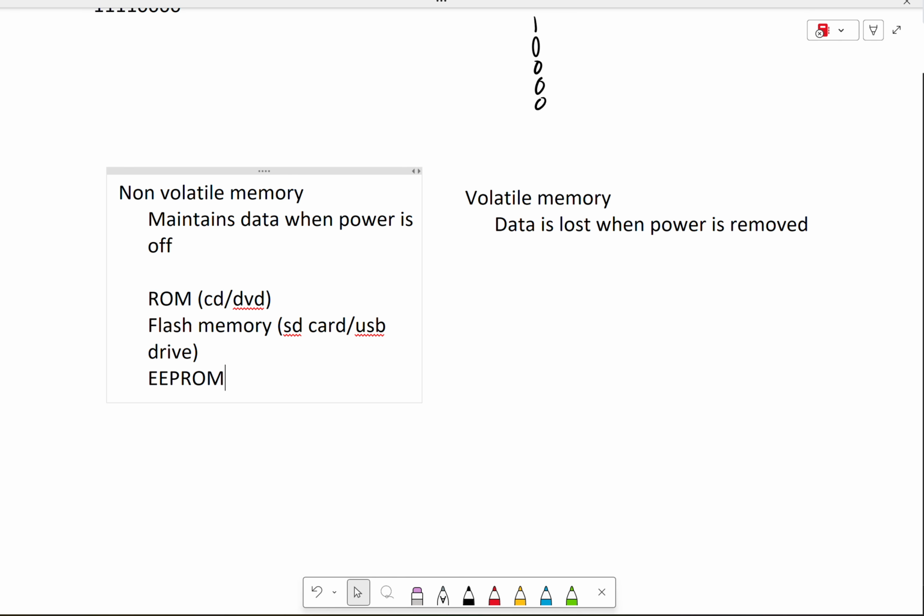Okay. The ROM part of a controller, that would be the part that's not really programmable. That would be the part of a controller where basically it knows it's a controller because that's how it's built and that's what it is. And then when you plug in your service tool to the system that has that controller on it, now you can reprogram certain parts of the controller, but that's the EEPROM that you're writing that data to. But when you're updating your trim files or you're recalibrating your shift points on the transmission, those types of things, it's the memory in the EEPROM that gets programmed. Okay.